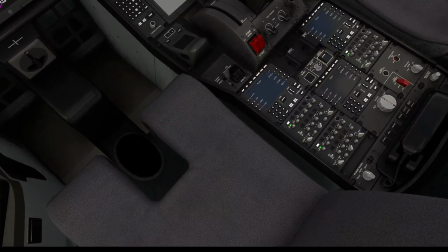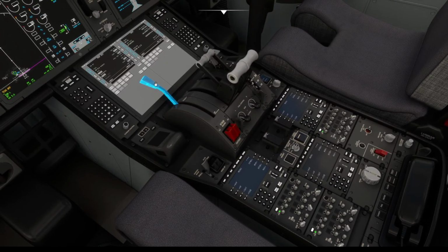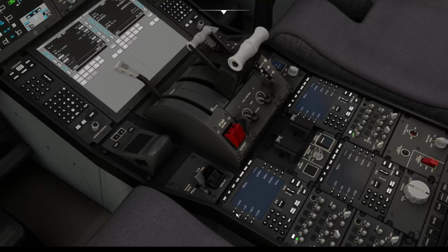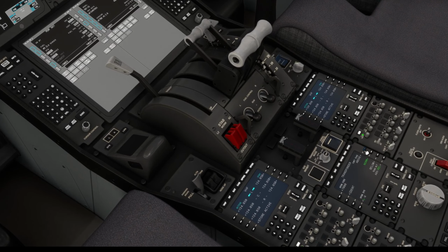All right, coming down here, make sure the speed brakes are down, stab trim, everything's normal, engine cutoff, flaps up, and go to VHF, and select the transponder here. So this should be at above. Okay. So yeah, usually you would toggle this to above during the climb out.